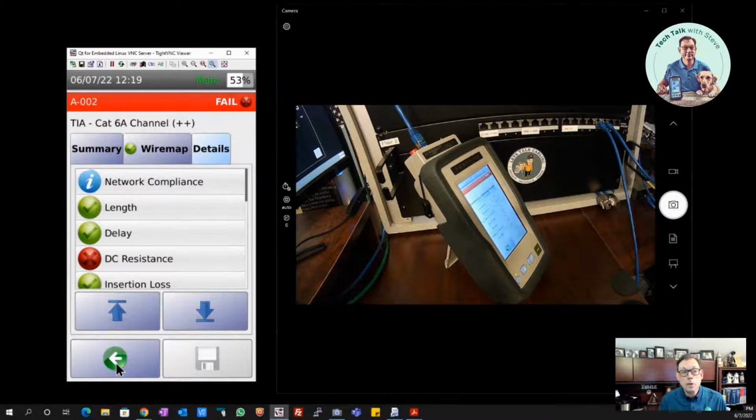So beyond that, you've got what's called a PoE load test, and there are several testers out there that can do this. You connect to the cabling, you do an initial discovery, you see that there's PoE there, and then you demand the load from the switch. So you're seeing, once that load is on the wire, can I actually get that power there? And that's an important part of the test, because just seeing that you have voltage isn't really going to be enough in many cases. So, we go back to that whole resistance issue, that I squared R equation and everything.